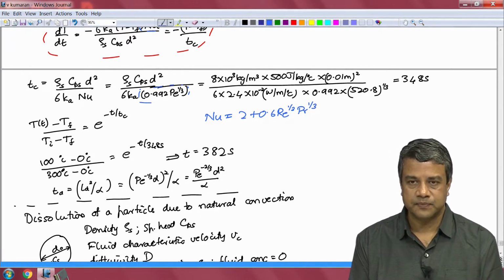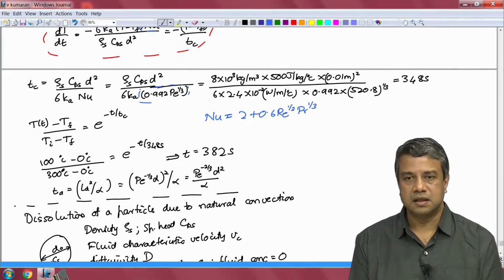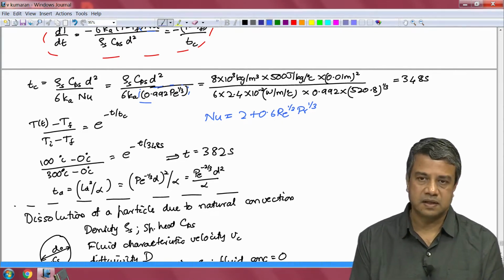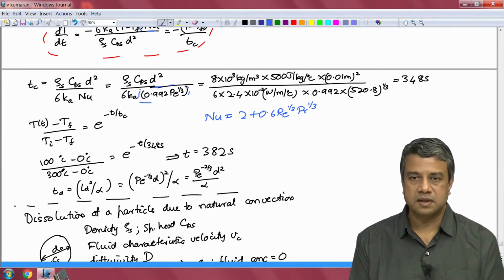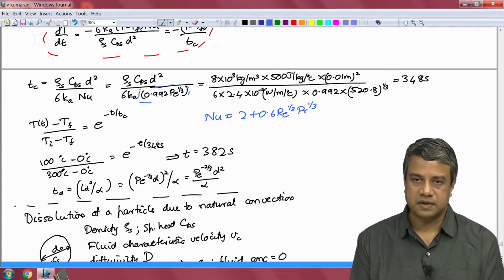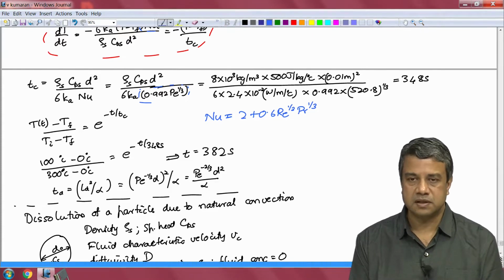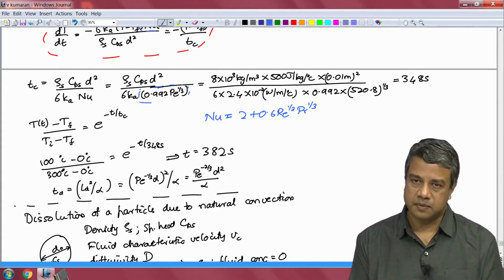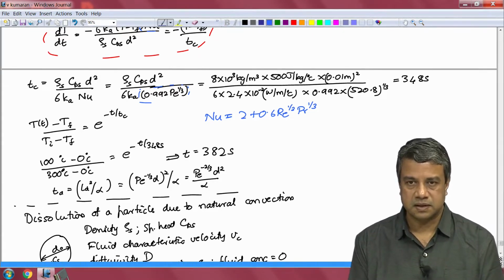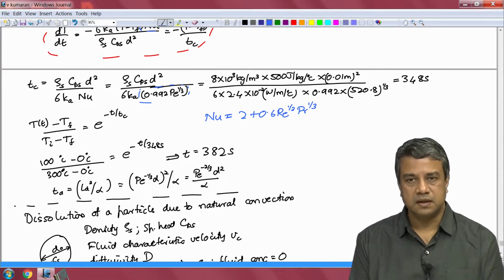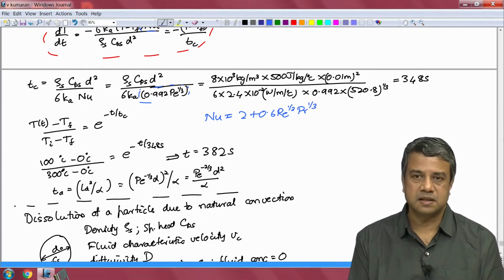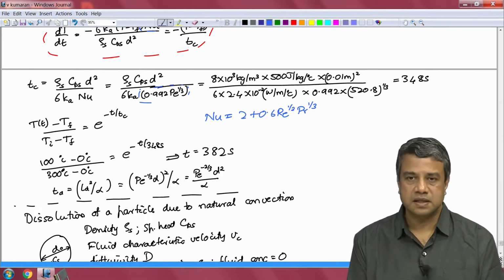or the length scale is much smaller than the characteristic length of the object. The length scale for diffusion at high Peclet number is much smaller than the characteristic length of the object, in case of spatially varying configurations. In that case, you can use a correlation that is derived assuming that the temperature at the surface and the temperature far away are constants. So, as long as that principle is satisfied, you can use other more specialized correlations as well in the same balance procedure.